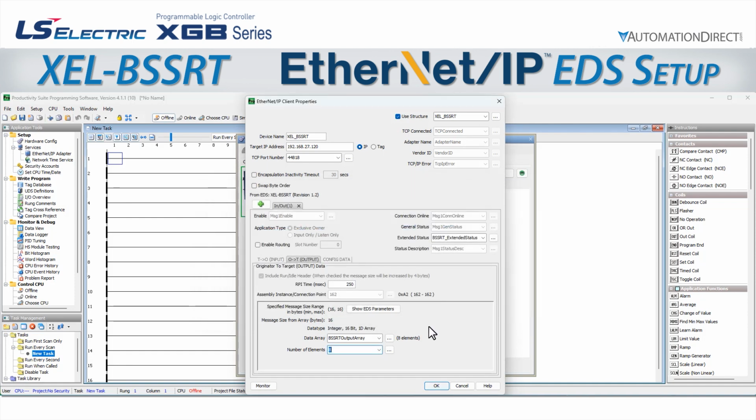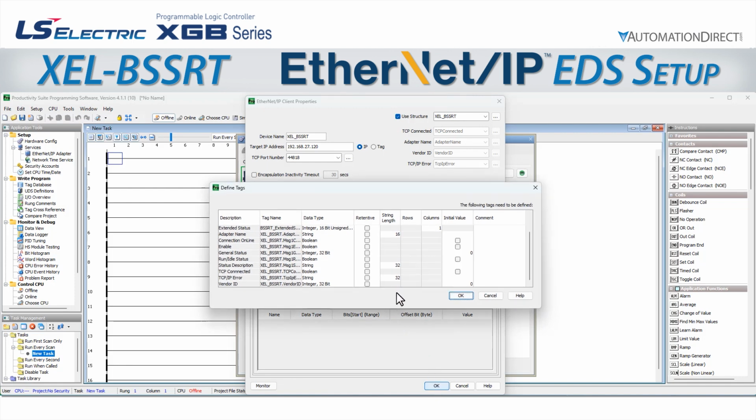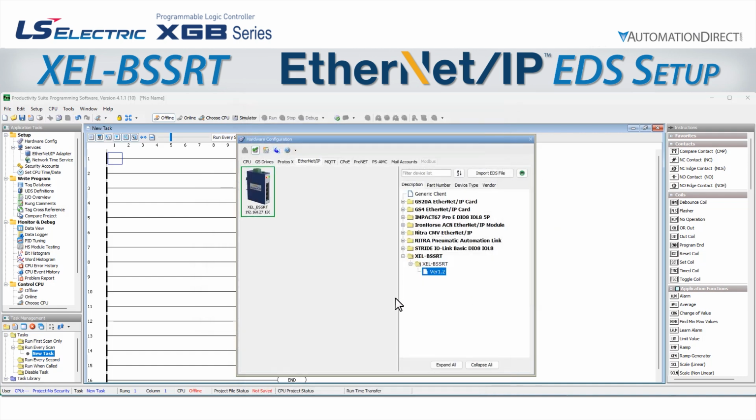We can take a quick glance at the Config Data tab, but there isn't anything to set here as the config data size is 0 for the BSSRT. Let's click OK and it will prompt us to create all the structure tags for the Ethernet IP client properties. We will leave them all at the default and click OK again.